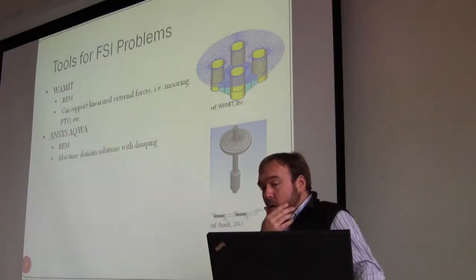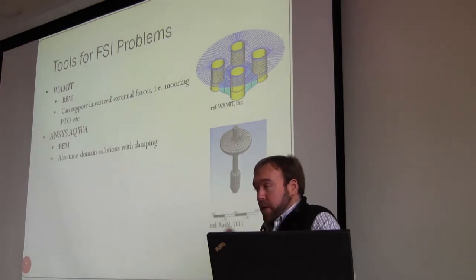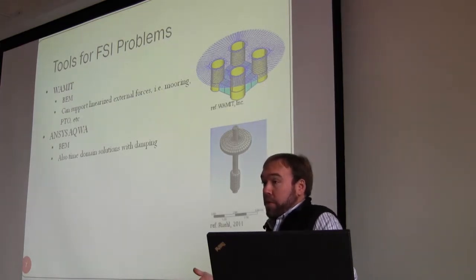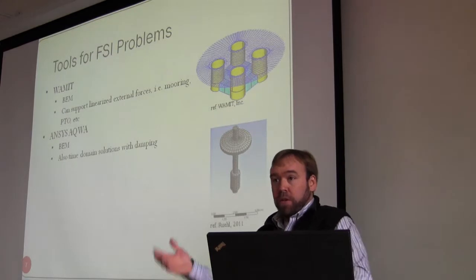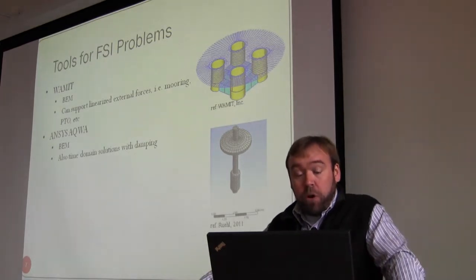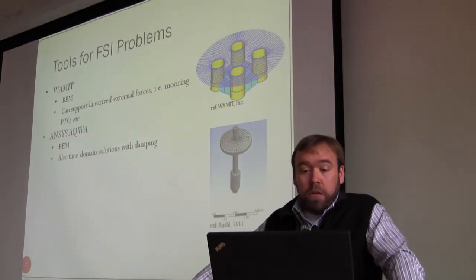So now let's talk briefly about some of the FSI tools that have been used. Of course, WAMIT is sort of the grandfather of them all. Boundary element method, and can support some linearized forcing. It's pretty limited in that case.